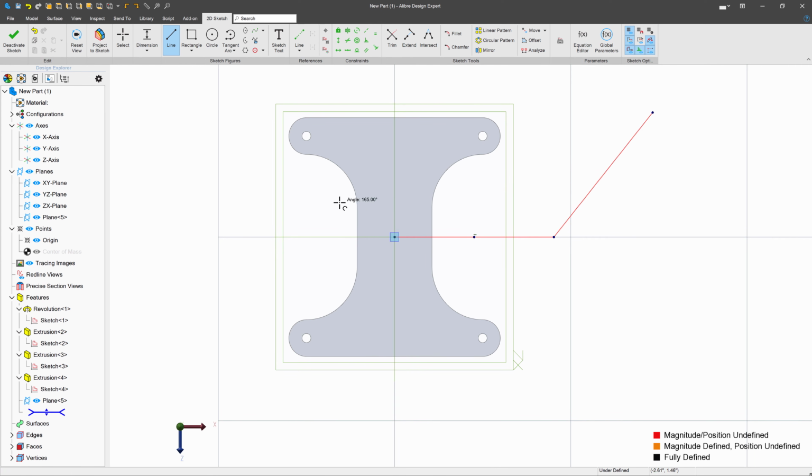We'll make a lever right there. We'll call this, how about 7.875? From here to here, we'll give that a dimension of 45. I'll go 5 here, and then I'll add a smooth bend using a sketch fillet.